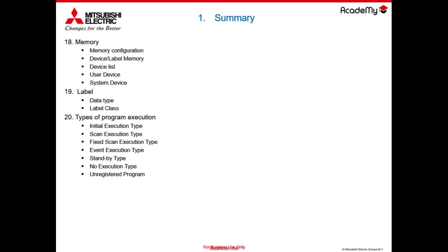And in this case, for these module labels, GXWorks 3 gives the possibility to add them, to integrate them into the project. Therefore, to make them our own, and precisely, these module labels will give us the possibility to program, therefore to interface in reading and writing, if required, clearly with the smart modules that are present in our configuration.